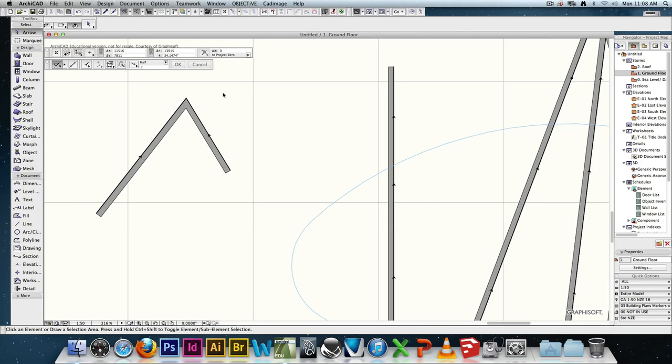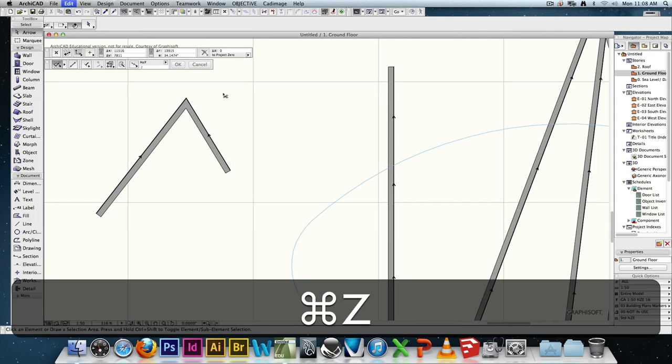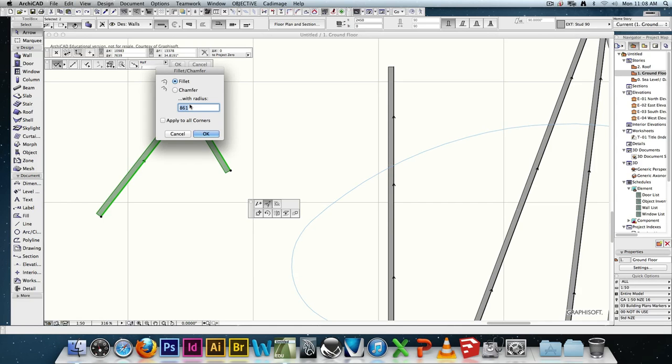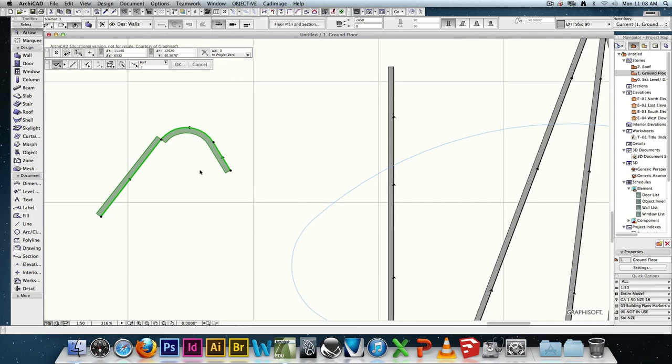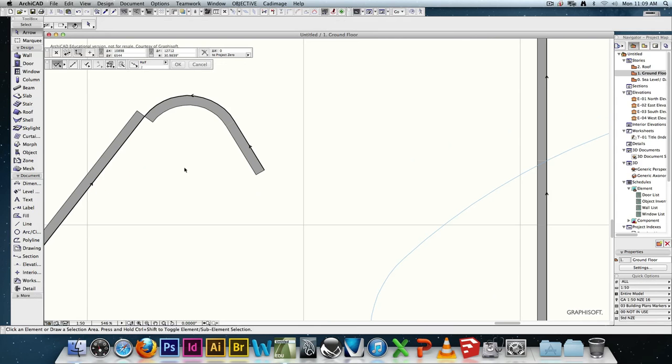And that fillet is a classic example because of the way that it's filleting. In fact, if I do it again, you'll see the reference line and how it changes. So let's say I put a 500mm. Oh, there, it completely screwed up. Yeah, you can see that the wall's coming around, it's on the wrong side, and then it flips. Yeah, it just can't do the math. There's no way you can get that to work any other way.